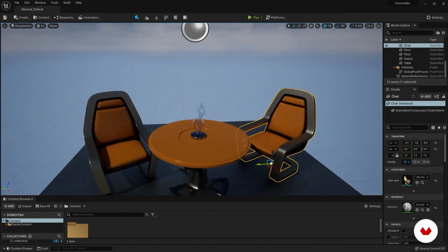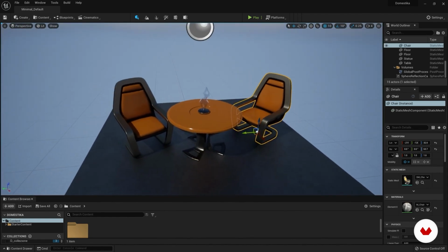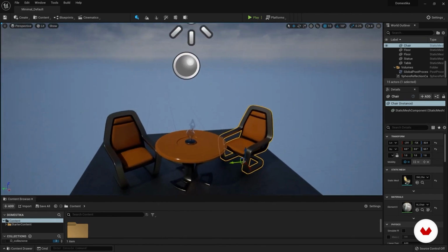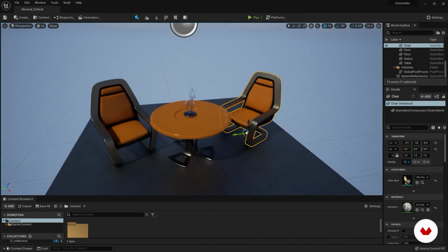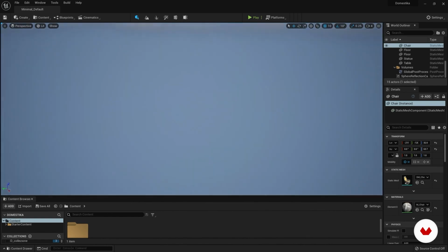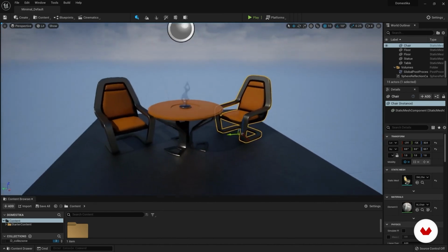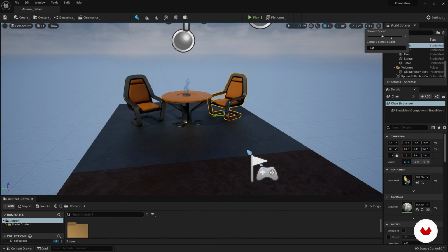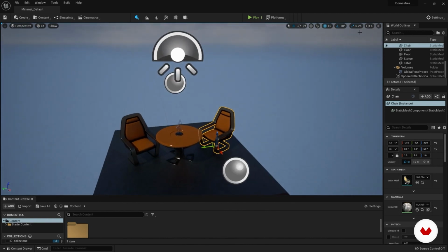Another important thing is that you can manage the speed of the camera in two ways. One is by holding the right button and moving the mouse wheel. Turning it towards us, the maximum speed of the camera decreases. If, on the other hand, we rotate it in the opposite direction, the speed of the camera increases. This same setting can be found here, top right. Camera speed and can be controlled via this slider. The two are independent. That is, moving the wheel will not change this value.